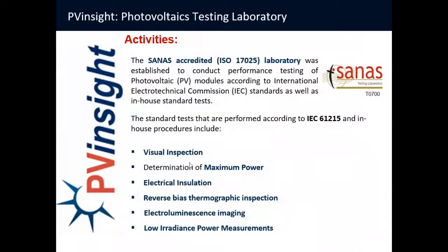So the Photovoltaics testing lab is part of PV Insight, which provides SANAS accredited PV module testing services. Some of the tests I've described in some detail in this presentation. We offer vision inspection and maximum power measurements, as well as the electroluminescence imaging, which we discussed during this presentation.